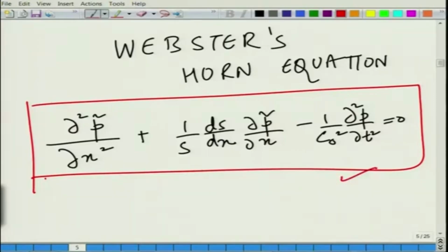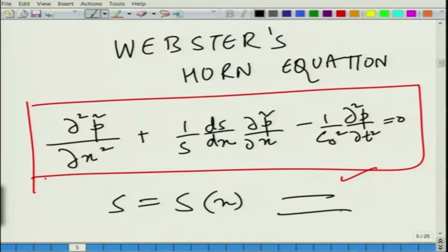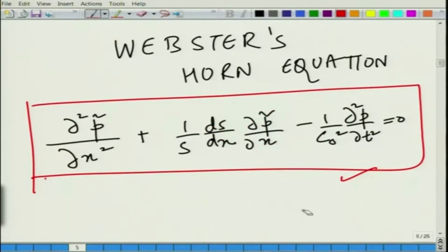This will be our objective, and S here can be any function of x or z, you see that. So, obviously, when S is constant, that is if you have a uniform pipe, S is a constant, say alpha, some constant. So, d dx of S is 0. So, because this term is 0, the entire term goes away and we get the well known equation for the one dimensional tube. So, that is a special case, but right now, our focus should be to derive this equation, which we will do in a while.